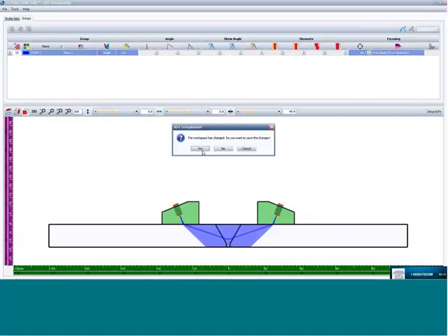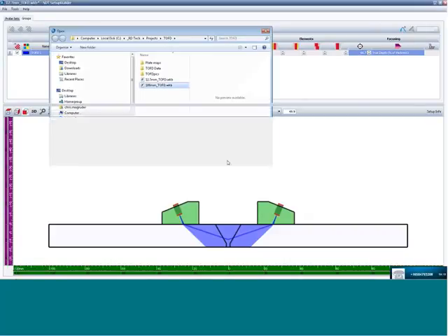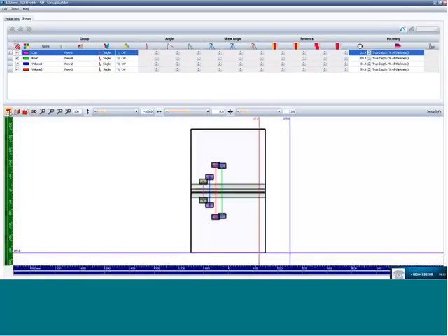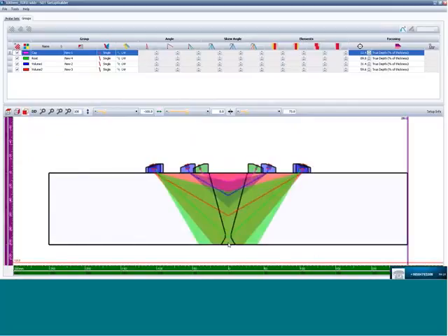It's faster to do on the instrument. But where we see a multiple configuration setup, like we do here, where we're using 4 independent TOFD groups to inspect a 100 millimeter vessel, we would start out with a cap group using small, high frequency, and it would become larger and lower frequency towards the bottom zones. In this instance,